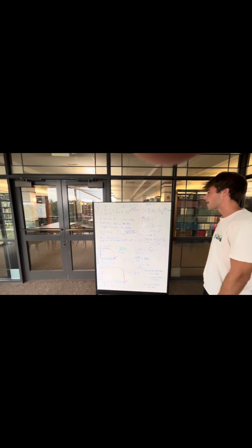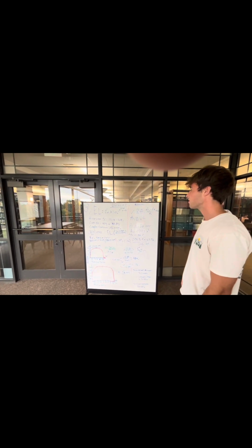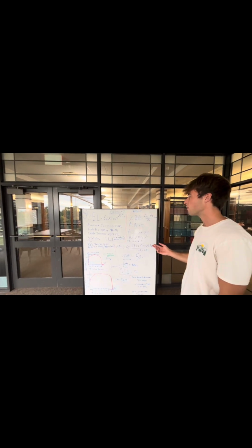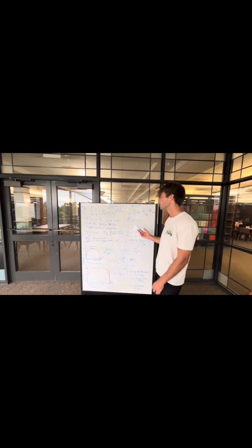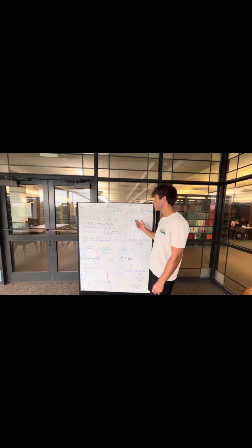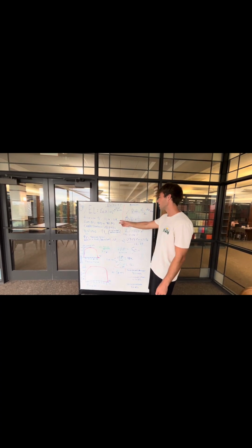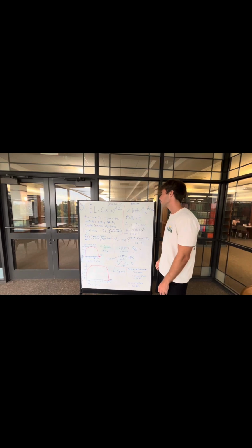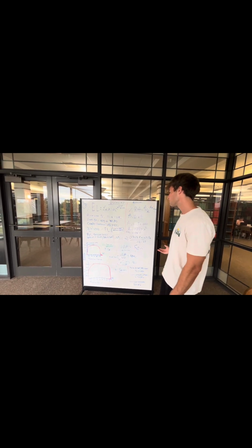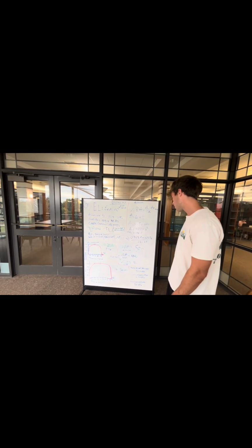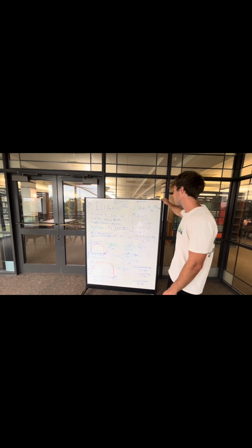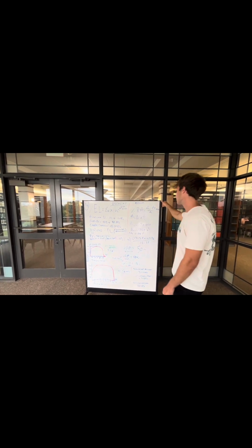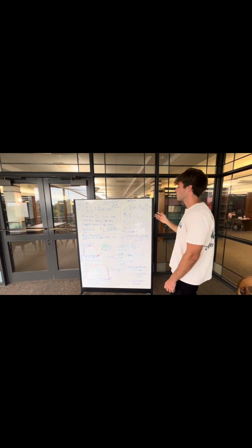From the graphs, we can determine that the εf of aluminum is around 0.132 and steel is 0.429, which we can make into percentages by multiplying them by 100. And then copper, for reference, has a percent elongation of around 45%. Then we still have to find percent reduced area for whatever material we're looking at, and in this case, it's aluminum.